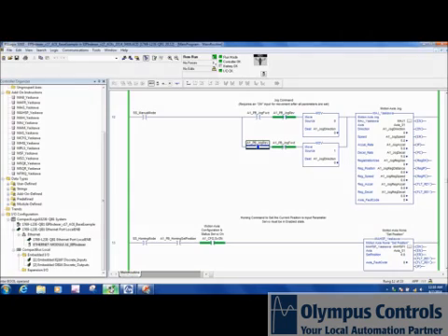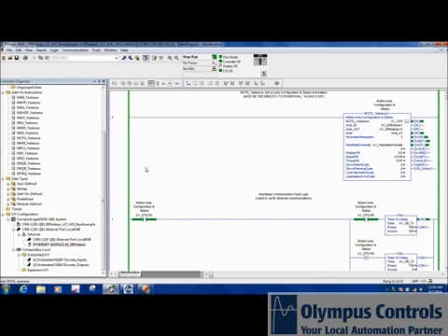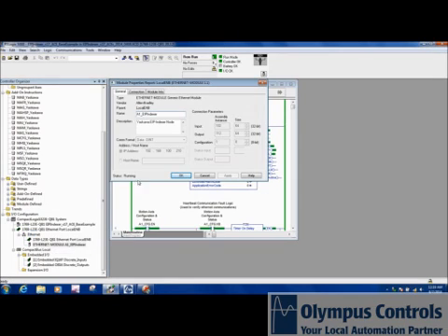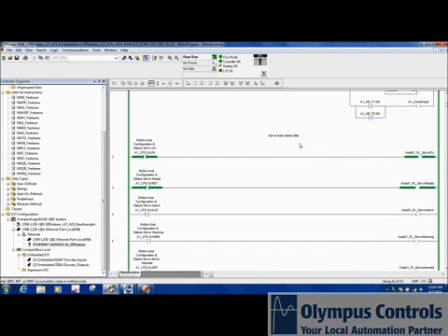If I open up my RSLogix 5000 programming software, I see that I have a Yaskawa sample project preloaded and running inside the PLC. You'll also notice there is a servo drive module mapped under the Ethernet port of the PLC. There's the Ethernet IP address of the servo drive, and I see the running routine where the drive is configured.